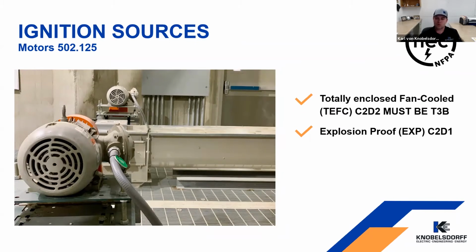If we're in a class 2 division 1 location, then we have to use an explosion proof motor. The tag on an explosion proof motor will list the class and division that it can be used in, and it has that T code rating right on it. A lot of times your explosion proof motors also have what they call thermals or P-leads inside of them, which are basically a thermal device that's built into the motor that opens up at a certain temperature rating to make sure that that motor case temperature never rises above that location's explosion limit.